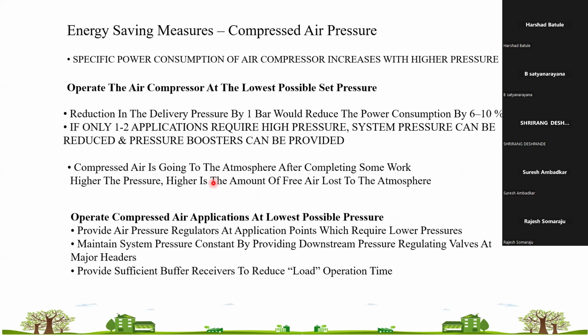Or if any compressor is placed in an isolated room where the exhaust of the compressor, majorly in an air cooled compressor, is not passed through a duct or outside the room, and it circulates in that particular room only, you are in disaster mode. So the location of the compressor is critical. You need to think of good air quality, a dust free environment at a lower temperature.